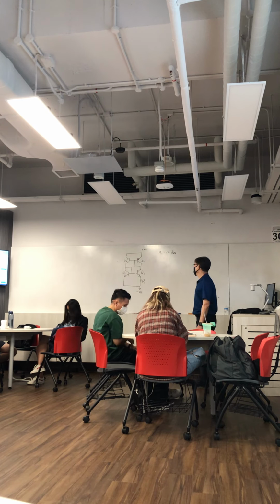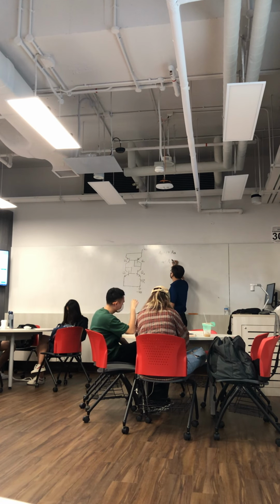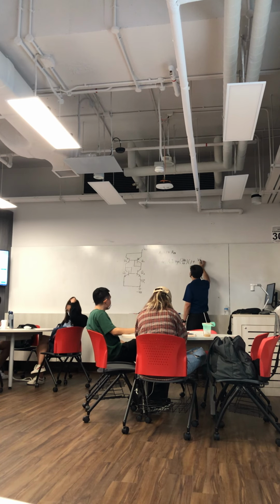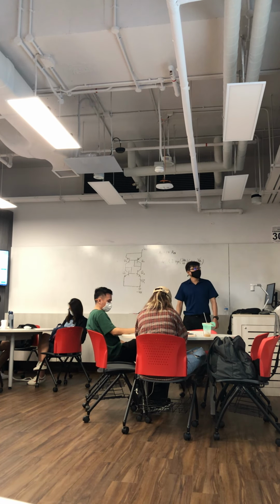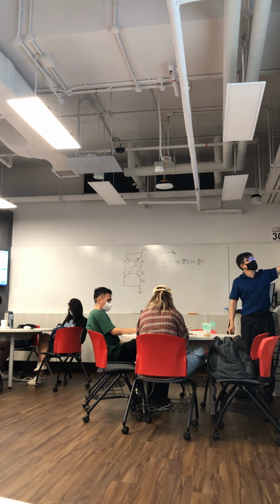Okay? So can I just recall, have you recalled, the collector current of the transistor, you take into account the emitter area, saturation current, exponential VBE over VT, then 1 plus VCE over VA, right? So if we ignore, see what the question says, assume infinite current gain.